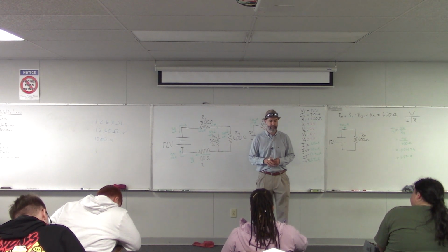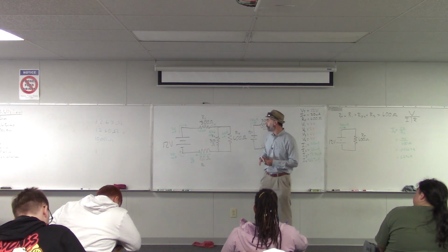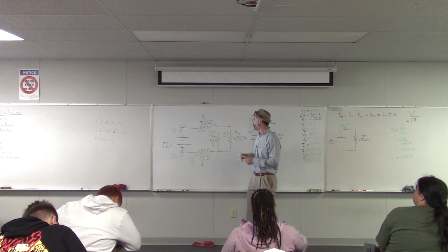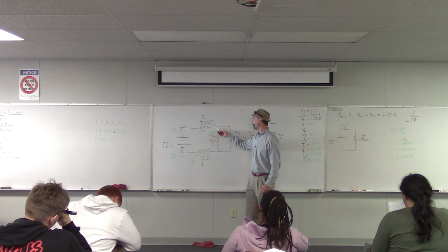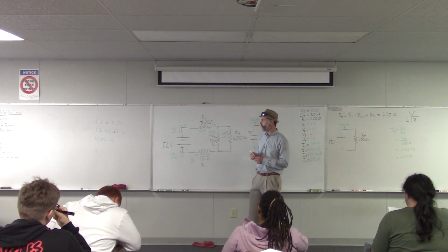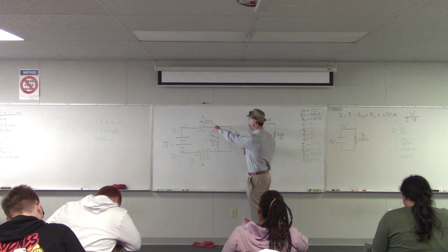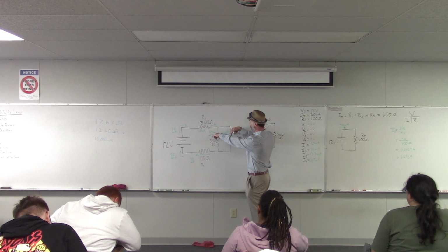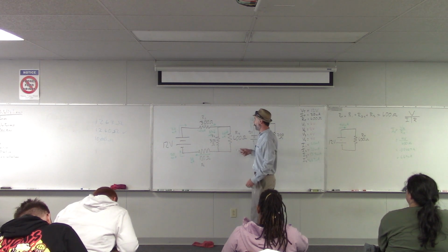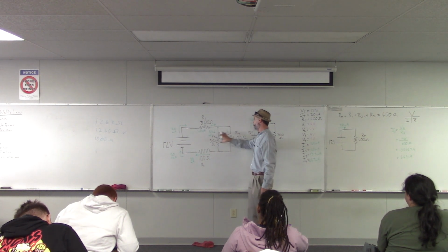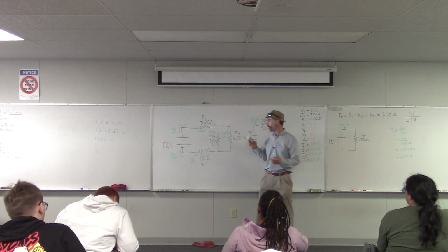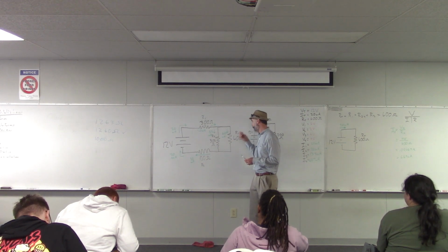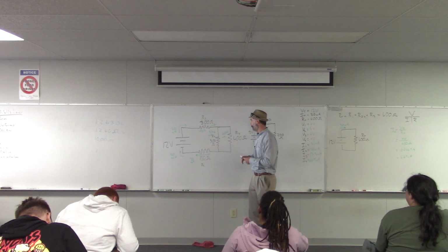So let's see if that law is holding up here. How much current do we have flowing into this junction? 20 milliamps. And flowing out, we have 13.3 over here and 6.67 over there. Do those two together add up to 20? Not exact numbers, but yeah, darn close. Close enough.